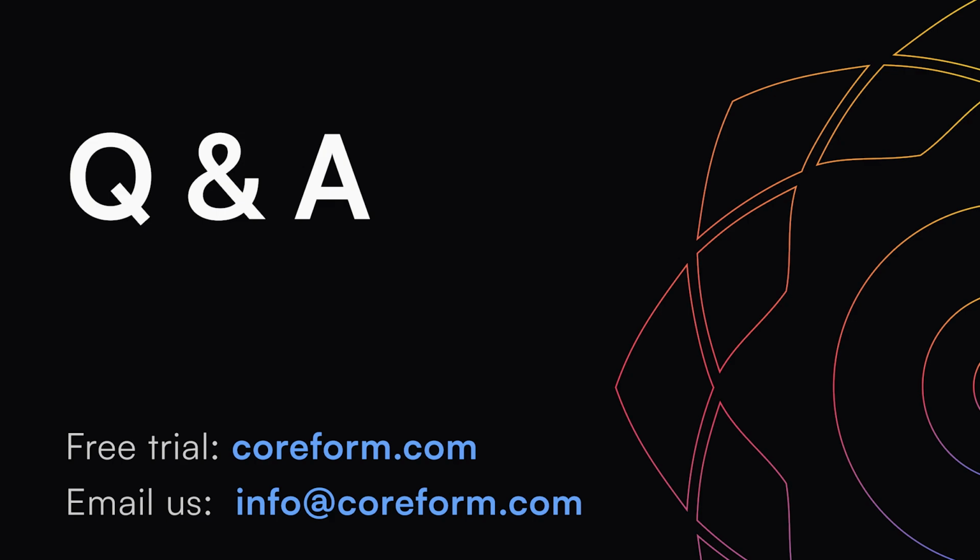Yeah. So as far as interactions, essentially anything from a workflow perspective, anything that you can assign to geometry. If you're in Abaqus CAE and you have a connector and it says pick the surface type for the primary region, as long as you can pick a CAD entity for that on your IGA region, then it'll work. That's just because we don't generate the mesh until after you submit. So there's not a node for you to pick, but we inherit those sets and make sure that we can handle stuff like connectors as well as contact.